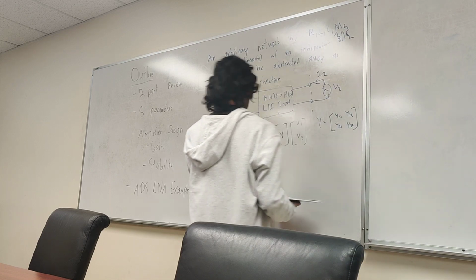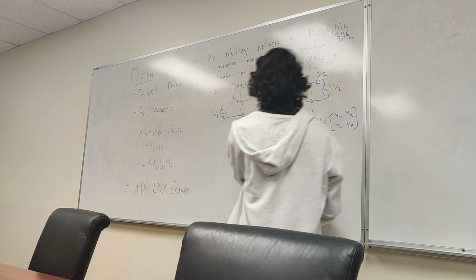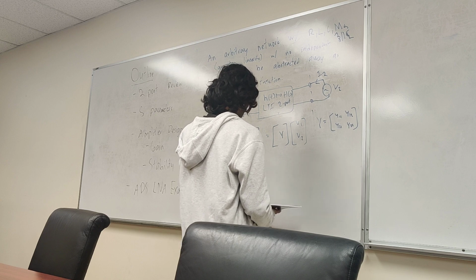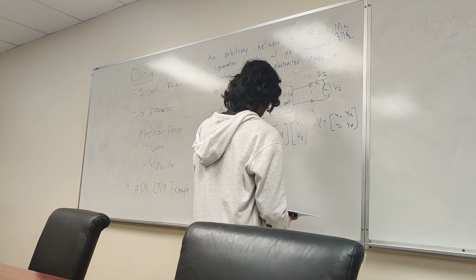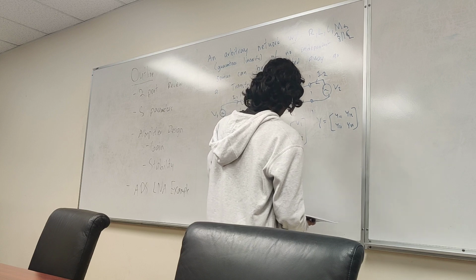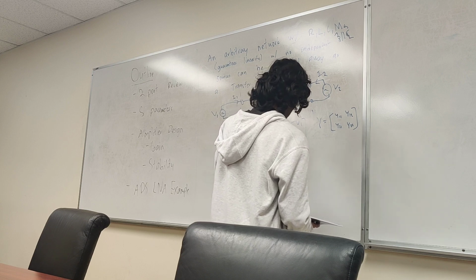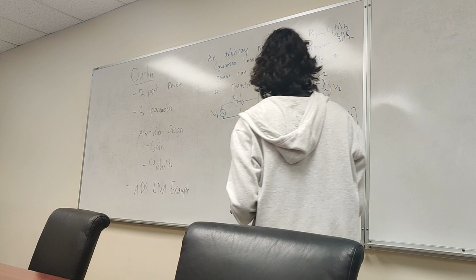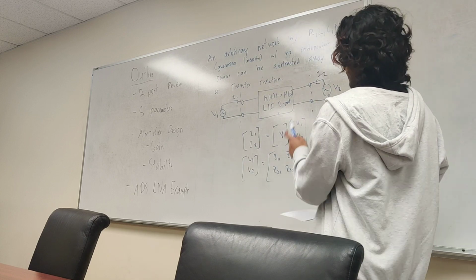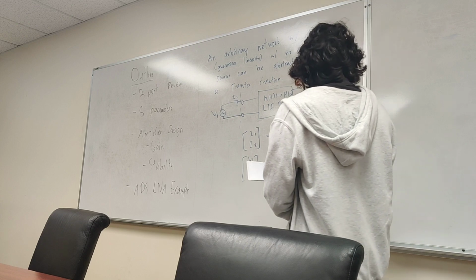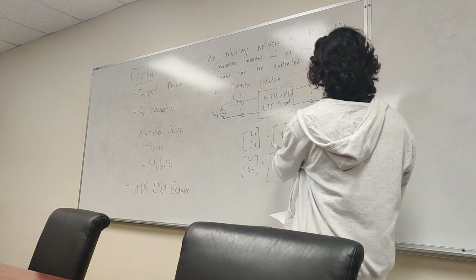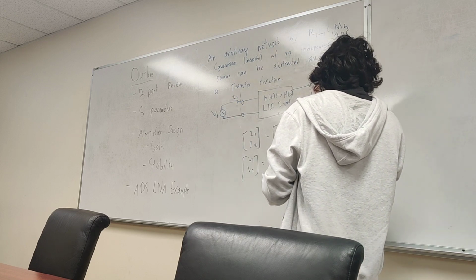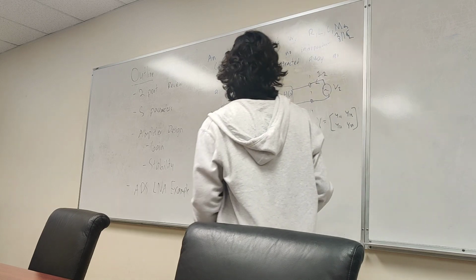That's the tricky part. There's another representation we can do here, and this is called Y parameters. We can do impedance, which we're more familiar with. So we can do V1, V2 equal to Z11, Z12, Z21, Z22 times your I1, I2, just like that. This kind of makes sense, right? We're all good with this? Okay. Call these Z parameters. And effectively, again, we know this. All we have to do is take our input signal, multiply, get our output. Now, I'm going to erase this.